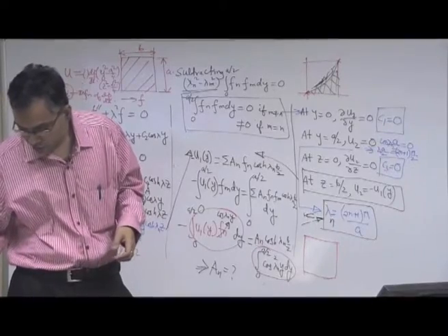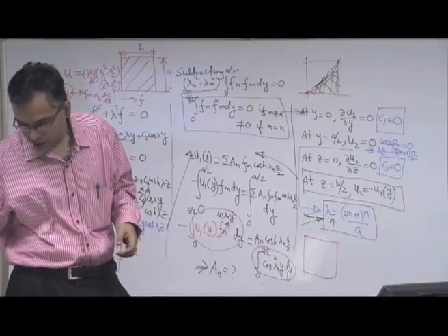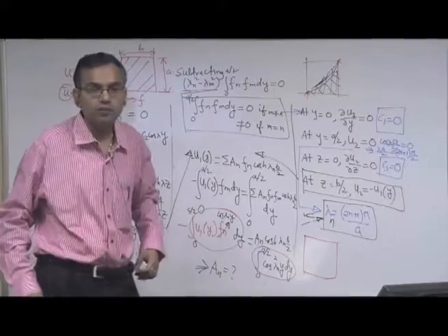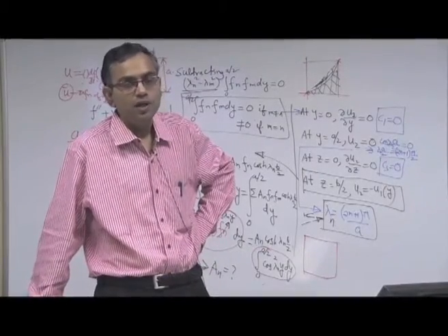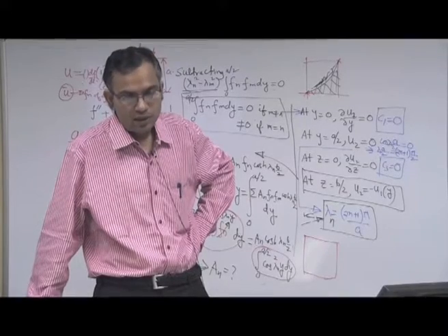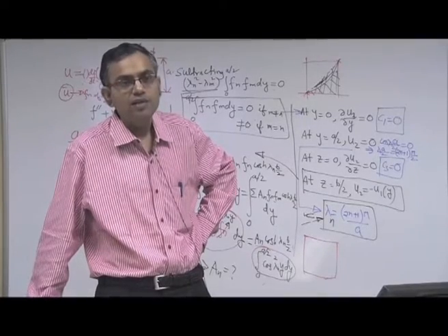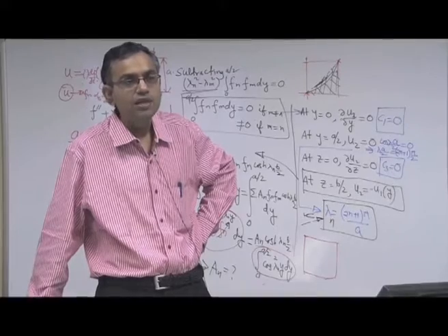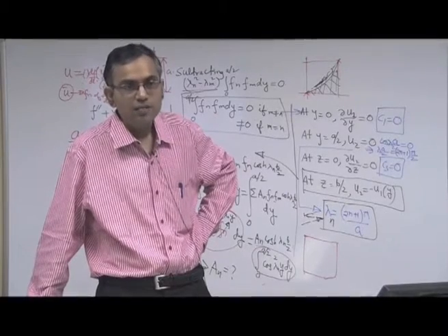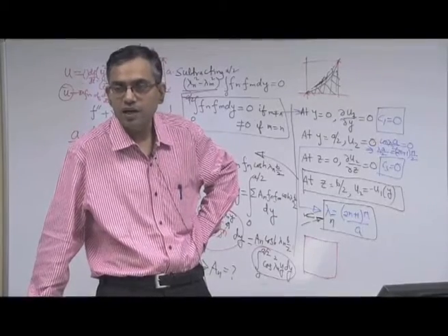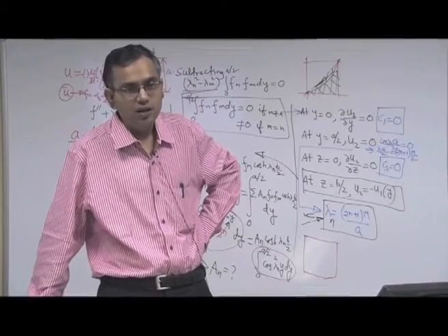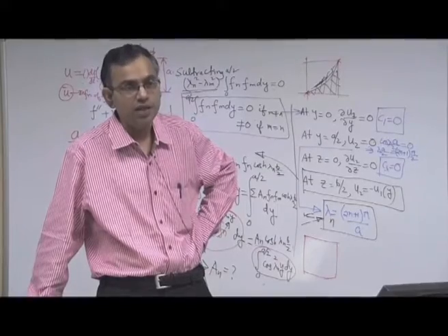Okay. So we have worked out certain cases of steady fully developed laminar flows for cases where it is unidirectional, I mean basically one dimensional variation, that is u as a function of y only, that is the parallel plate channel, and a rectangular channel where u is a function of both y and z.